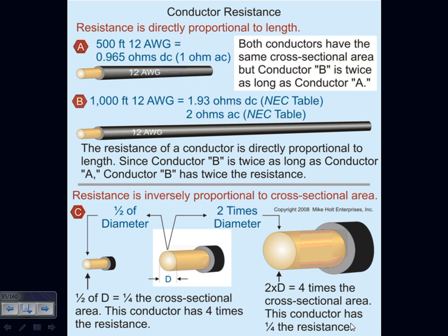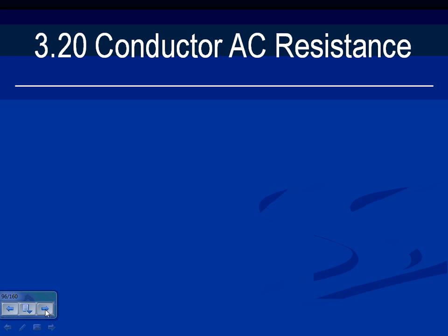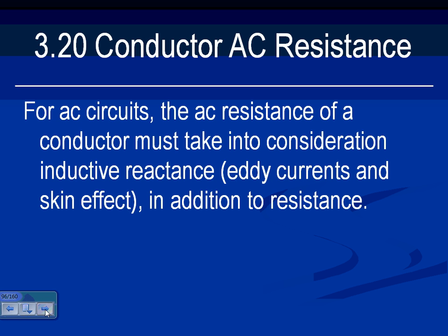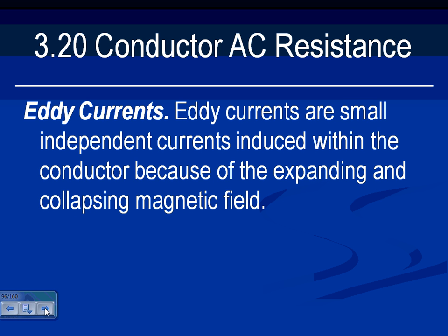And later on when we start doing voltage drop, guys, every conductor in chapter 9 is going to have an impedance. We're going to be using this impedance to calculate the voltage drop and so forth. But for the time being, remember, it's not just the coil that has an inductive reactance. A coil can have an inductive reactance, and conductors, when you have a long run of them, can have an inductive reactance that will affect the flow of current in it. Eddy current and so forth, the resistance.